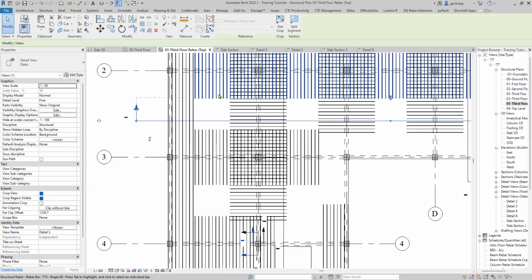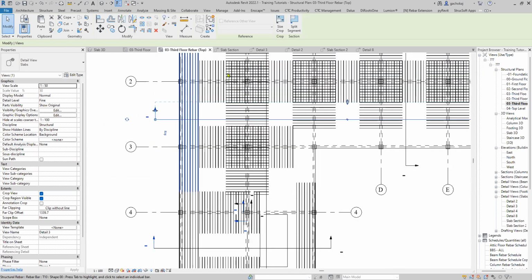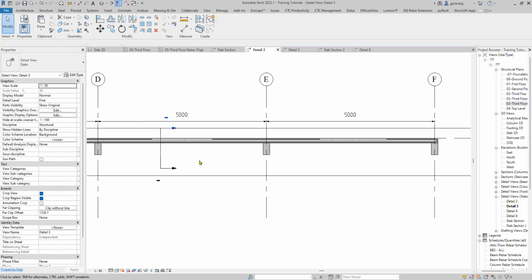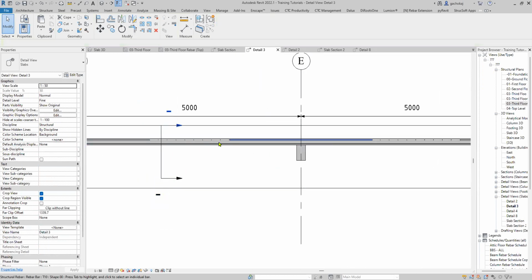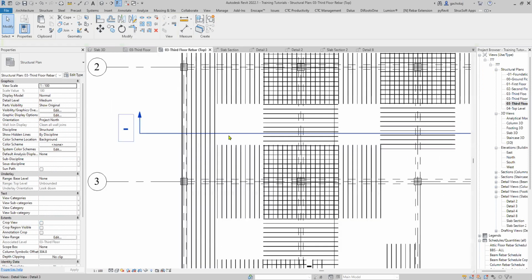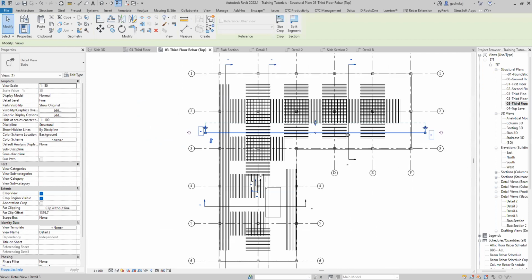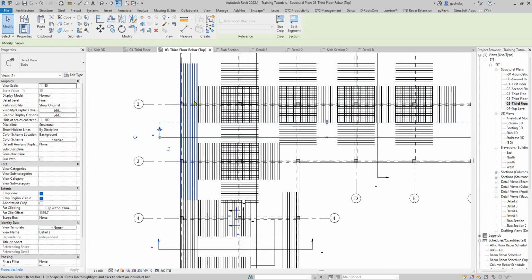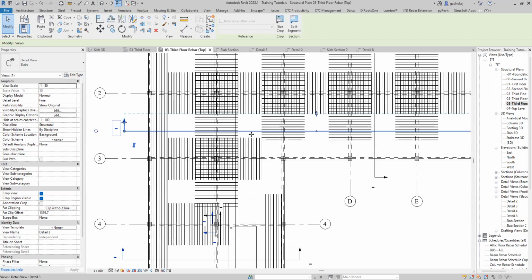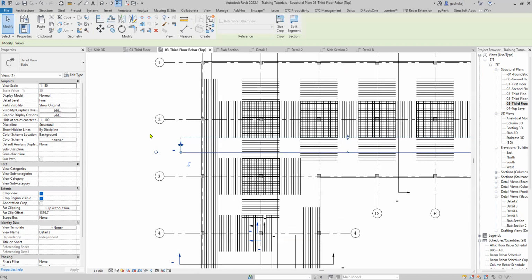Here, you can still do top twos here, nominal reinforcement, top twos here, and here. If you check, you see we need top twos, but you can do one, then copy it all along. That's the easier way. So I'll do this one between grid B and C.